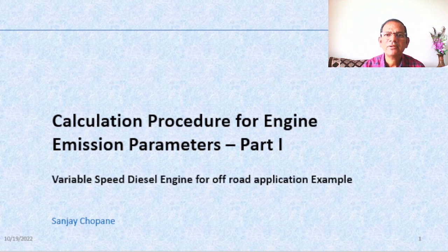The great advantage of this tool is that the engine designer can upfront estimate or assume some raw emission values, and using this tool calculate the cyclic level emissions and compare whether these resemble the engineering target and the limits. So with the help of this tool, the development time and iteration time can be significantly reduced. In the next slide, we will understand what is in it for you.